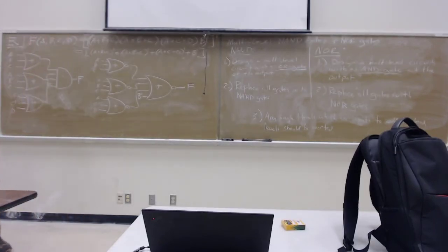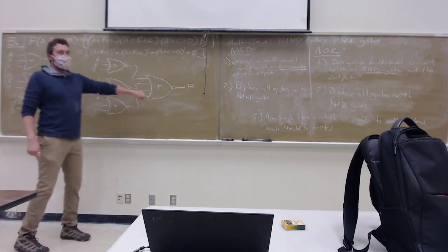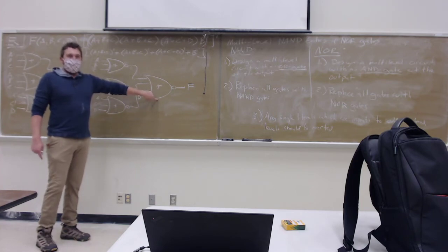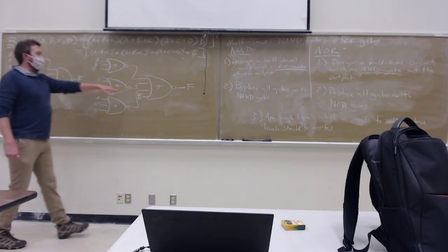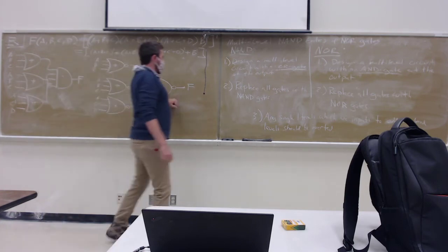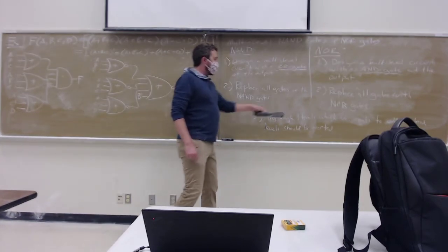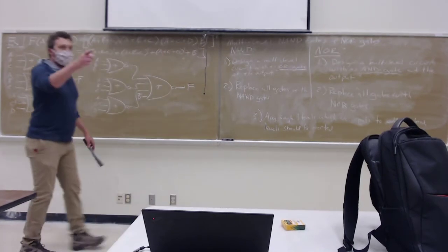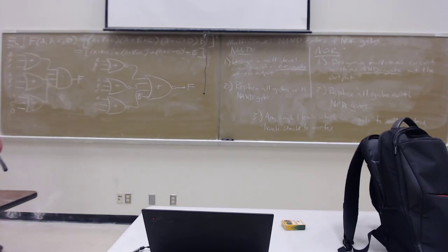I think it was in this class somebody asked, do you have to count the levels from one direction to the other? And I said yes, and it's going to matter. This is why it matters, because this one has to be level 1, so they can be odd numbered, so they can get their literals inverted. And then we would invert level 3 and level 5 and level 7 if we had those going all the way back. But the first one has to be 1, so that it can start off this chain. What's that? So it's even, you leave it alone. Exactly. It's even, you just leave it alone.